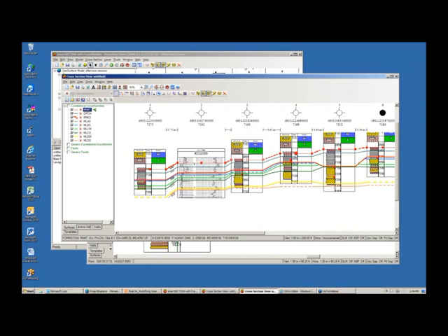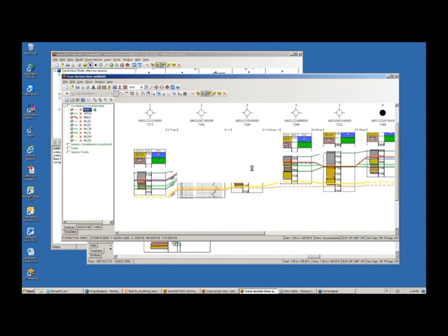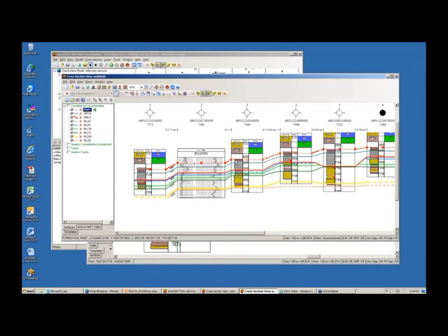What you're going to notice is that smartSECTION in the particular mode that I've got is going to try to pick the top for you. You will always know that it's smartSECTION's best guess because the square will be hollow and the line will be dashed. So you will know that that's smartSECTION's best estimate based on its model, based on all the other picks that you've made, as to where in general that pick will be. You can choose to ignore it if you want. We can also choose to even turn it off, which I'll show you in a minute, which a lot of people like to do.